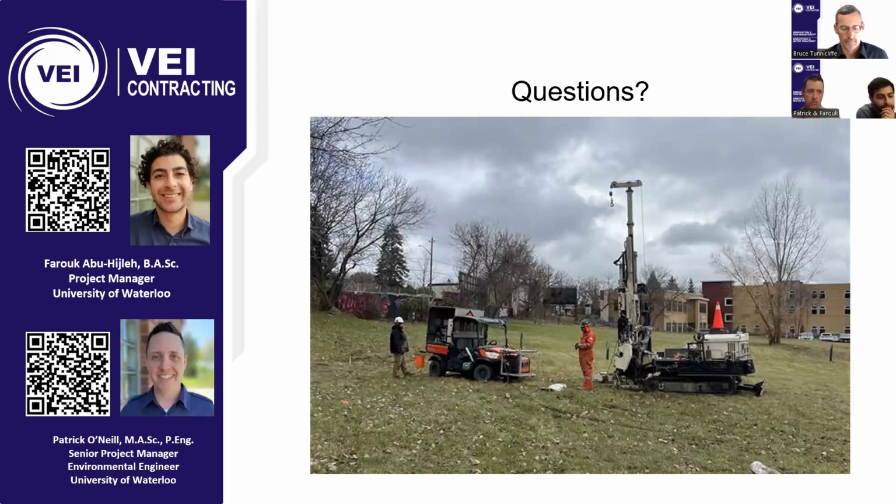In our site that we just looked at, it's not a massive site, and we've got major differences in the sand unit and where those silt layers are, and that really affects your overall dewatering plan. And for a very small amount of time, you can get that data in as quick as possible. So if you have done your hydro-G assessment and you haven't done construction yet, and you want to fill in those data gaps, you still have time to do it.